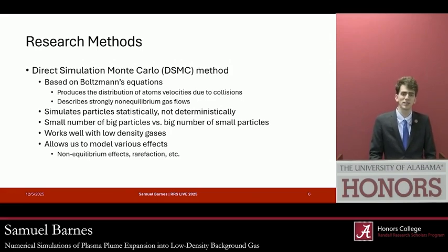So yes, the DSMC method can be expanded to all 3 dimensions. So you can use 1 dimension, 2 dimensions. You can have an axially symmetric sort of design. You can have it in 3 dimensions. In our case, 1 dimension is suitable enough for our needs. Really, the plume is not a pure line or cylinder or shape coming out of it. It's almost like a cucumber-shaped plume. But in our case, I think the plume splitting could be observed even in one dimension, and that gives us good computation. It takes a lot less time to run a one-dimensional simulation than a 2 or 3-dimensional simulation.